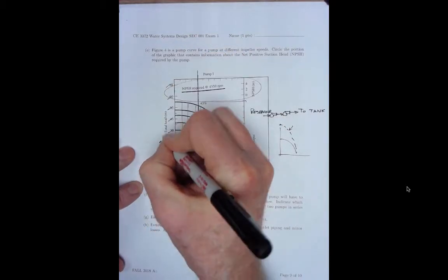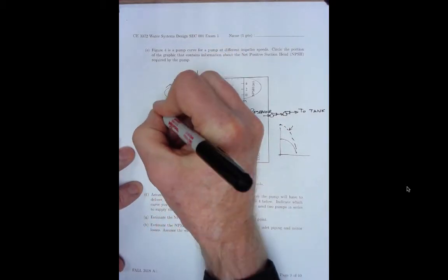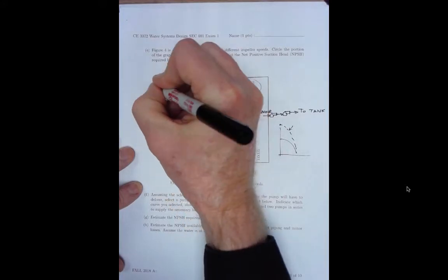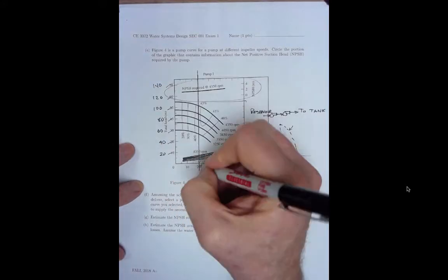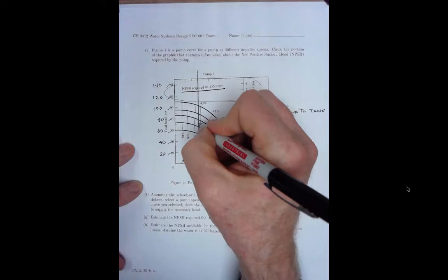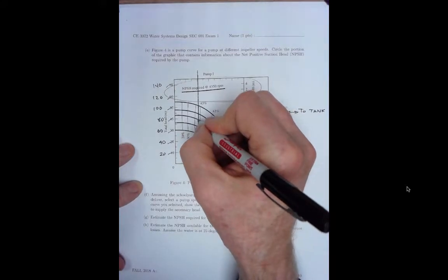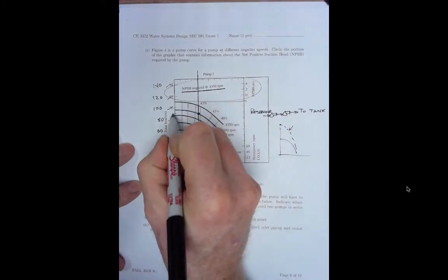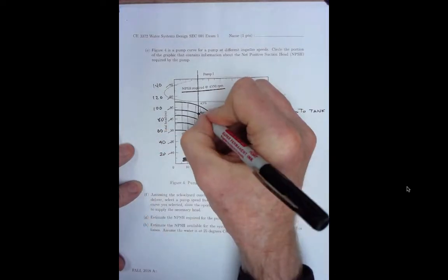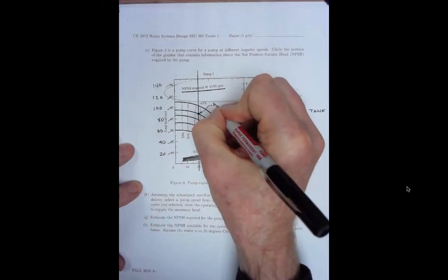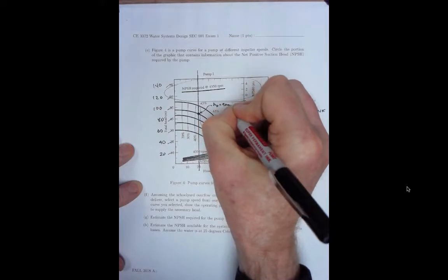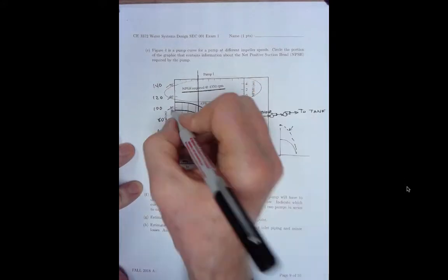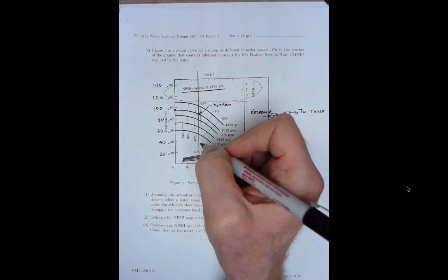20, 40, 60, 80, 100, 120, 140. Here's our operating point. We're after 88. So I look right about here, and that's a head of about 90 meters at 21 liters per second. Shut off